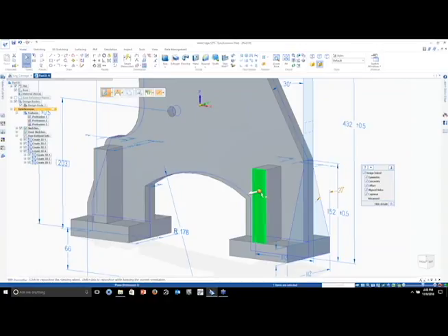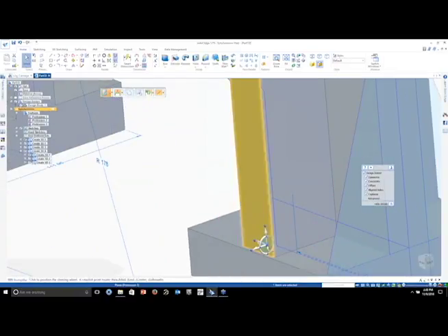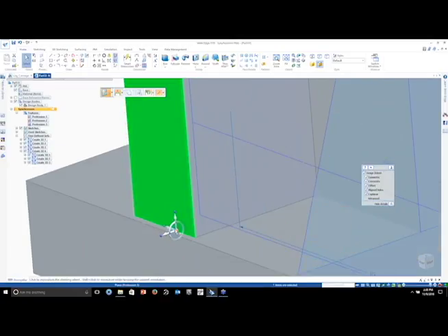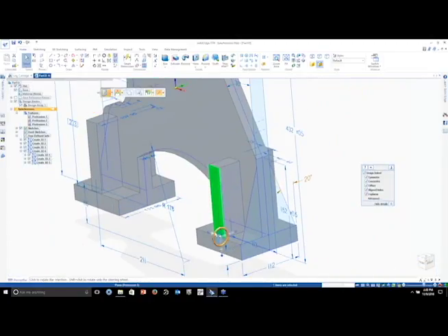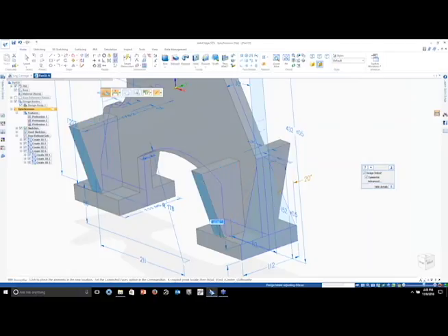All right, so once I do that, I can grab the steering wheel and start rotating around, and you can start looking for another key point to snap to. I want to change my key point back to, let's set it to all, so I find everything. You notice it's doing it on both sides. Well, the reason why is it's finding symmetry about the coordinate systems. It's finding symmetry about both sides. So now I just go find that endpoint, and there we have it. I think that should be all the dimensions turn blue. That looks good.